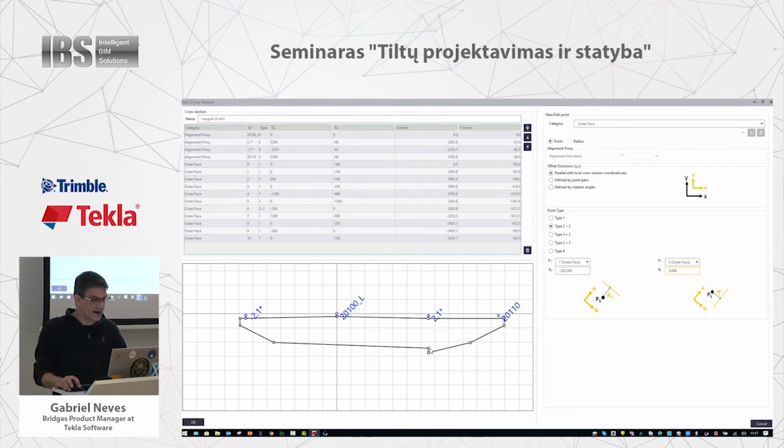Okay, I know I'm now playing with the vertical constraint with that point, and that one is playing with that. So let's put 500 just to see. Minus 500. So now this point is 200 below that point and 500 to the left from that point. This is not what I want to do.